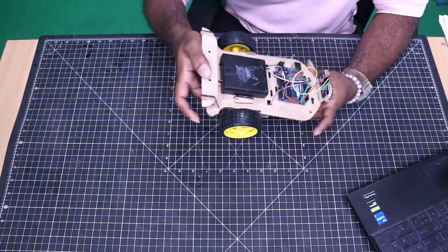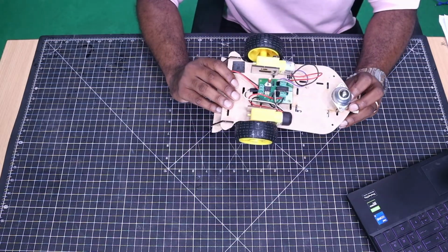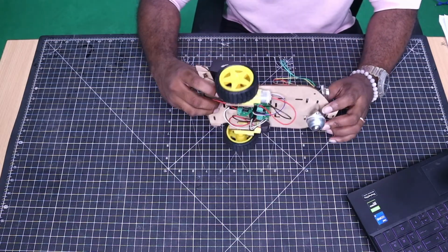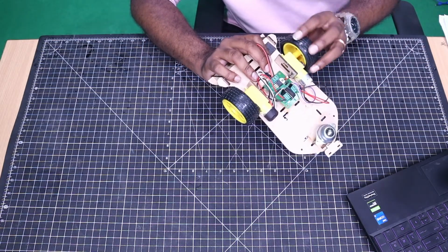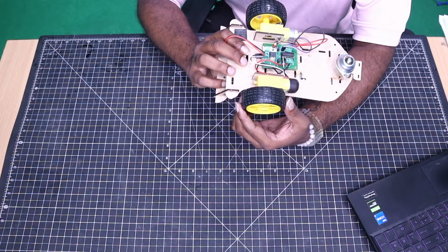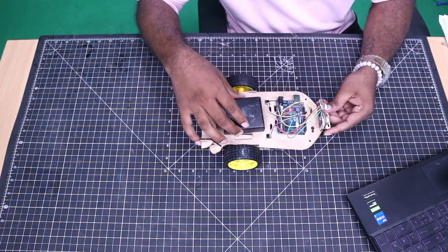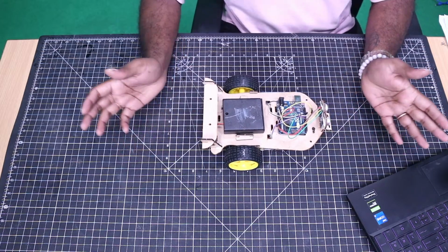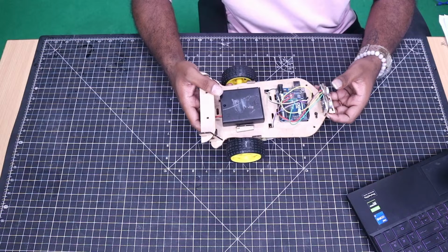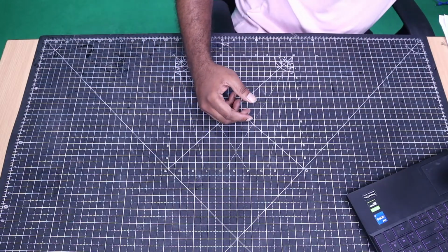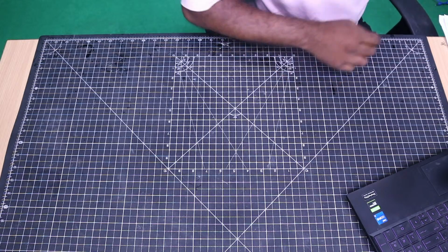It's using a battery. Yes, I have a battery pack here. It has an Arduino, it has an ultrasonic, and there are a couple of motors, and there's a motor driver. I'll tell you what the motor driver does. Basically, it distributes the power and controls the wheel, the direction of how the motor spins, left or right. Yes, it changes the direction. I've written a small program to make it go. If there's an obstacle, it'll go either way, left or right. You can program it. I'll show you one last project, and then we'll make one of these.